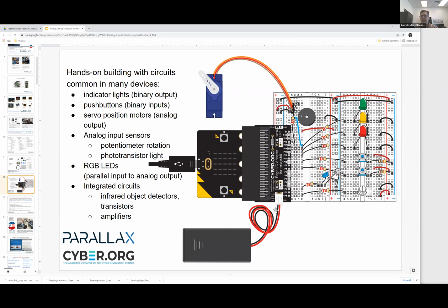And be careful, I see an error here that I need to go and remove everywhere it occurs. I believe the red wire is supposed to be on the left. So this is kind of showing you how to plug in the battery pack backwards. So be careful about that. Red wire on the left, not the right, as it is in this picture.